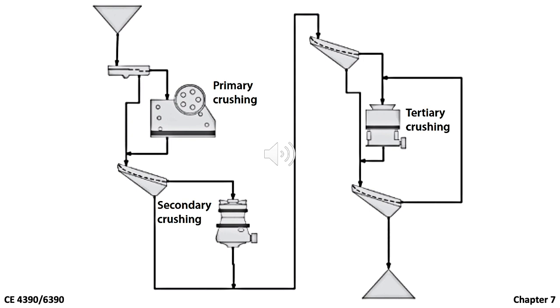Raw stones are first fed into the hopper, and then go to the first screen. Small sized stones that go through this screen will be transported to another screen, while large rocks will go to the primary crusher where the size will be reduced. The final products of the primary crusher are passed to the second screen.